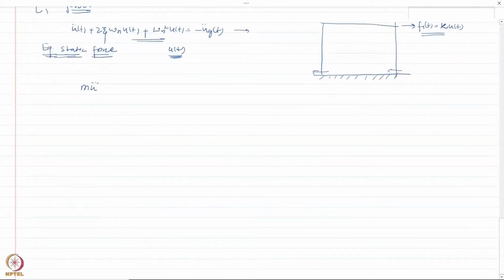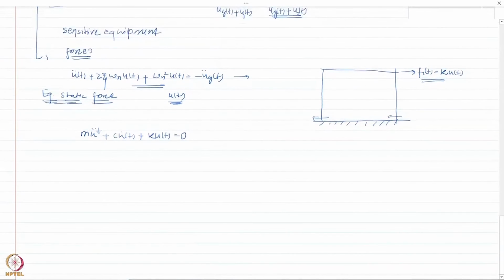This can be observed from the equation of motion. If you consider the total, absolute value of the acceleration, remember we had this equation here, plus k u of t. Somebody might ask: why is this external force k times u of t and not m times u double dot? Because in the end the external force is basically the total acceleration that the structure is experiencing, right? Mass times the total acceleration. So why not this force?